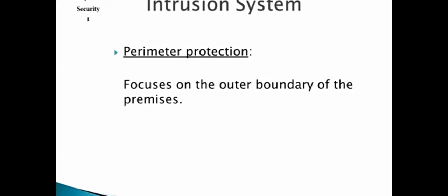Now, whenever you're setting up your fence line, we discussed that on Monday. You might want to consider putting in motion sensors on the fence, or a sensor that runs a microcurrent through the fence line or through a sensor wire that shows that it's being tampered with. So use this on your outer perimeter.